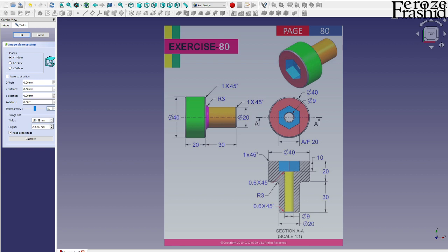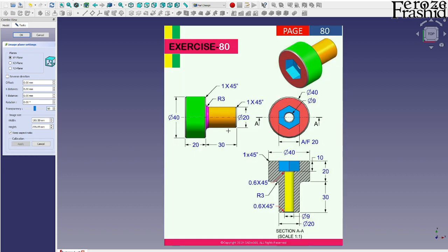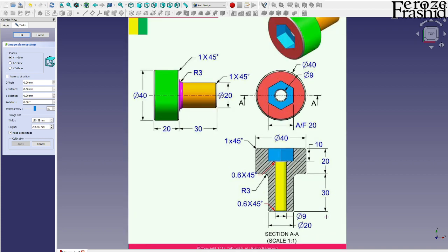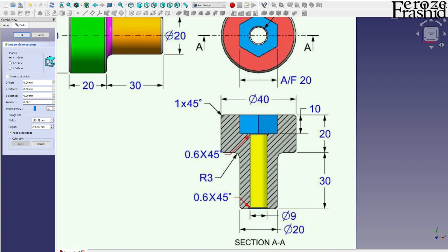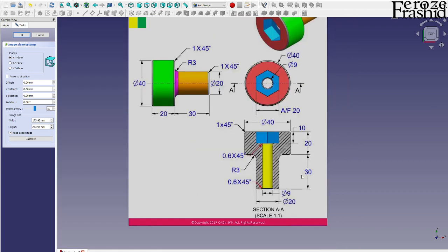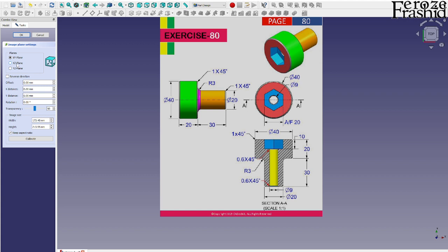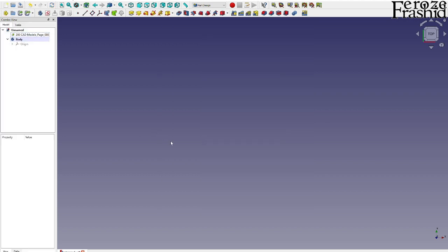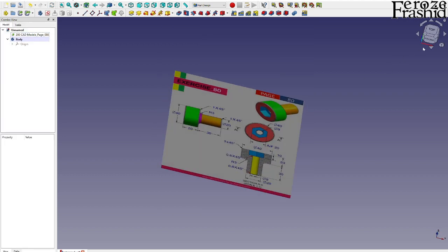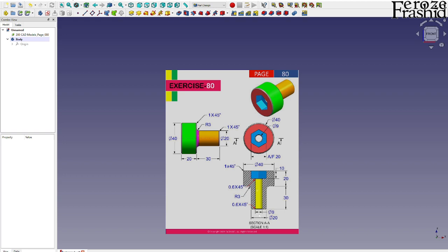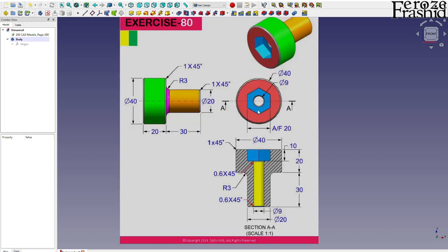And on this object, I want to keep working on the front face. So I'll place this object on XZ plane. Currently it's on XY plane. So let me go ahead and change that real quick and say XZ plane, and there it is. So there on the front side, I want to start working on the revolve part.